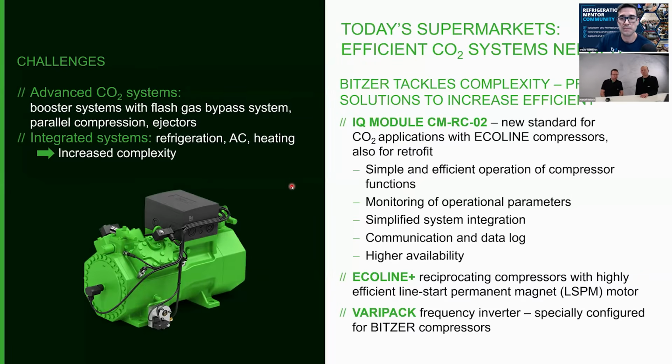With frequency inverter driven compressor selection, we had challenges with a high number of starts and stops, because if the compressor is too big, it starts and stops quite often if it cannot address the minimum load. And therefore, we have had some examples where we also did retrofits. We replaced Varistep with the frequency inverter. The situation with the frequency inverter in the wintertime was the compressor started, it went to 25 hertz, and after 1 or 2 minutes, it stopped again. Which was running fine for a couple of weeks or months.